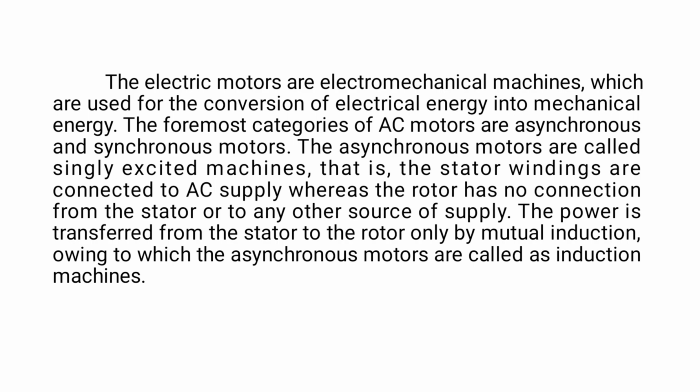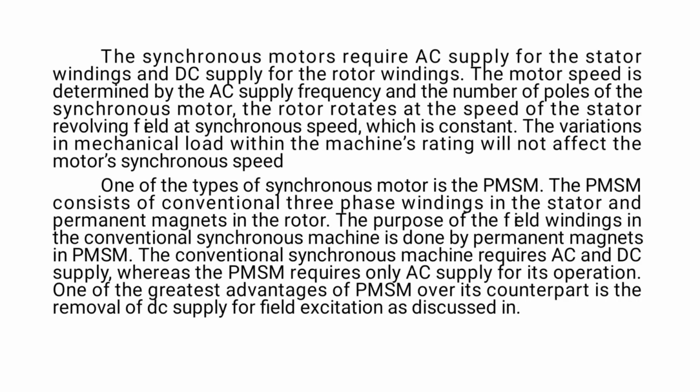The foremost categories of AC motors are asynchronous and synchronous motors. The asynchronous motors are called singly excited machines. The stator windings are connected to the AC supply, whereas the rotor has no connection from the stator or to any other source of supply. The power is transferred from stator to rotor only by mutual induction.